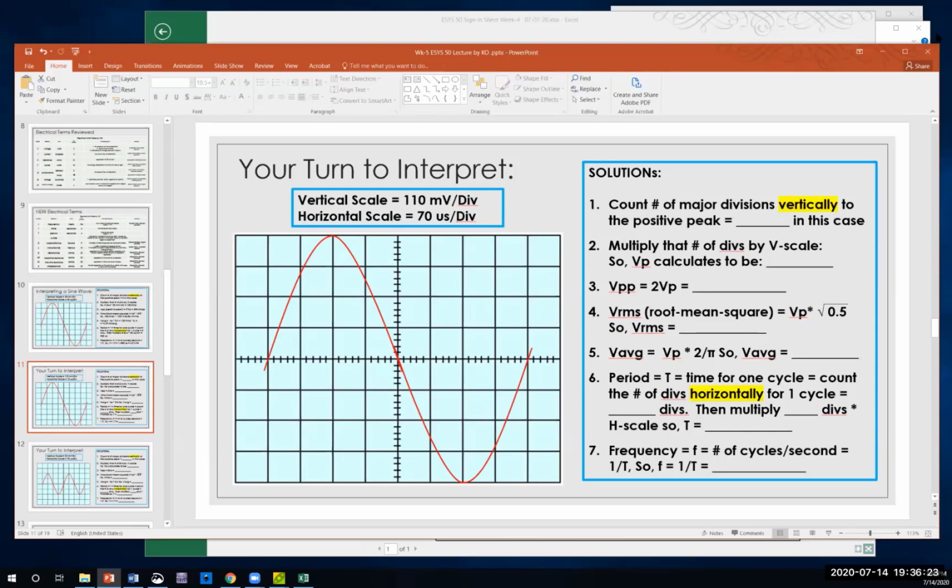Oh, no. Okay, so then that would be 1.79 kilohertz. Precisely. We have to key in the 560, and we have to remember micro as 10 negative 6. Once we key that in the calculator, then if you reciprocate that, then it comes out as 1.79 kilohertz.